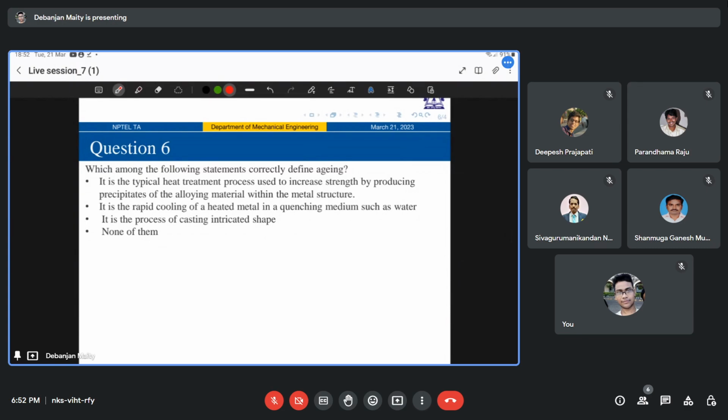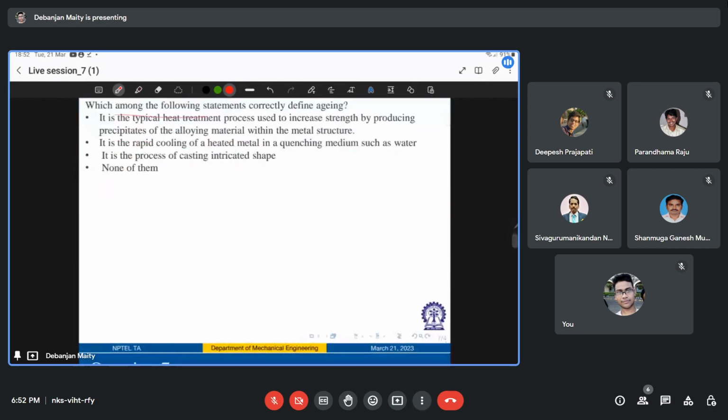Okay, I think this age hardening process we have discussed initially anyhow. Age hardening is basically a kind of precipitation hardening which we'll discuss in the subsequent discussions. Can you tell me any alloy which is a great example of precipitation hardened materials? What I can think of, there can be some aluminum copper alloy.